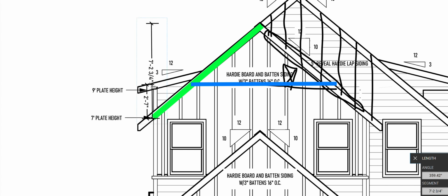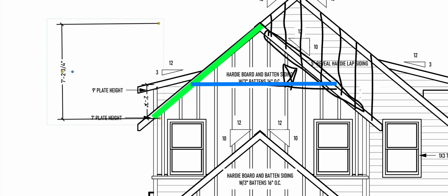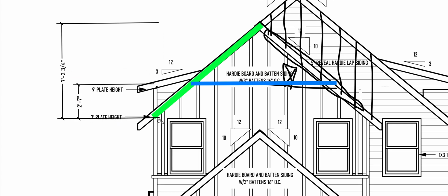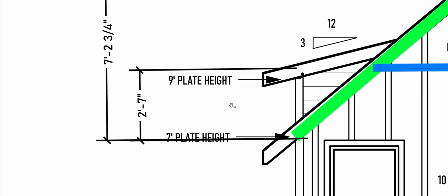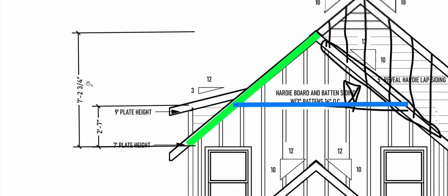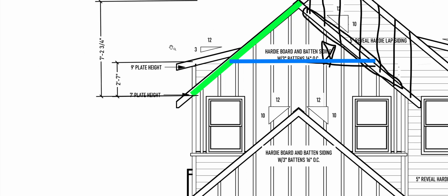And that is the height of my rafter, roughly above the wall. So I'm taking the wall height to the top of the ceiling joist, and the wall height to the peak of the rafter. This is HC, height of ceiling joist. This is HR, height of rafter above the wall.